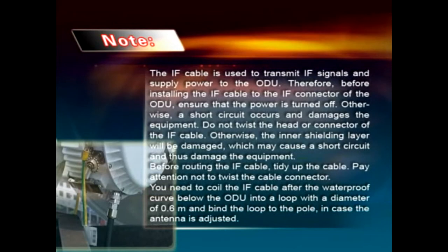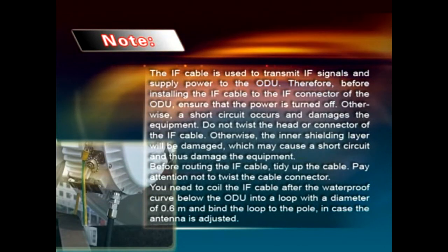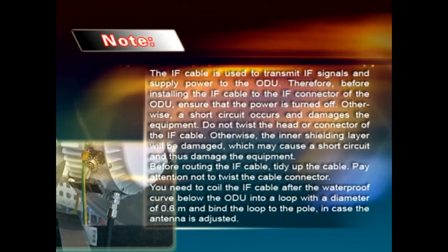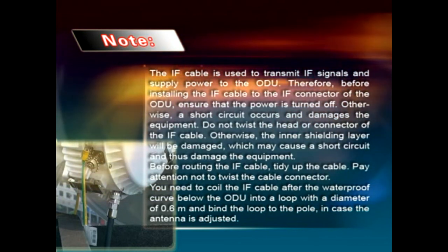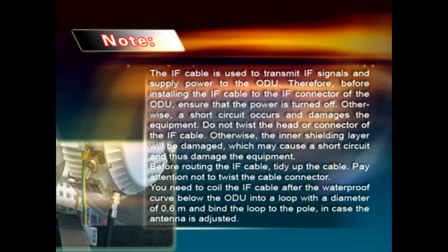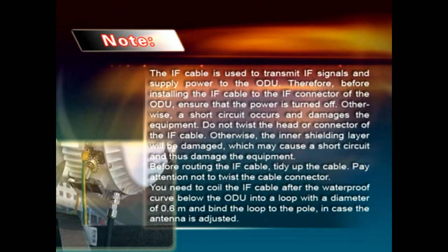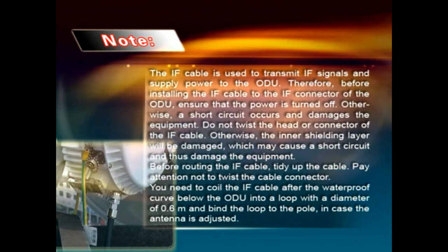Note: the IF cable is used to transmit IF signals and supply power to the ODU. Therefore, before installing the IF cable to the IF connector of the ODU, ensure that the power is turned off. Otherwise, a short circuit occurs and damages the equipment. Do not twist the head or connector of the IF cable. Otherwise, the inner shielding layer will be damaged, which may cause a short circuit and thus damage the equipment.